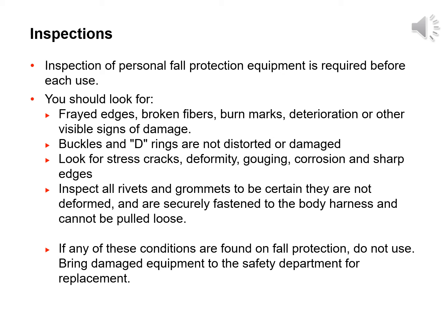The stitching should be intact and not torn or loose. The harness should be somewhat soft and flexible and not stiff from dirt or contaminants. Check to see that buckles and D-rings are not distorted or damaged. Look closely at all components for stress cracks, deformity, gouging, corrosion and sharp edges.